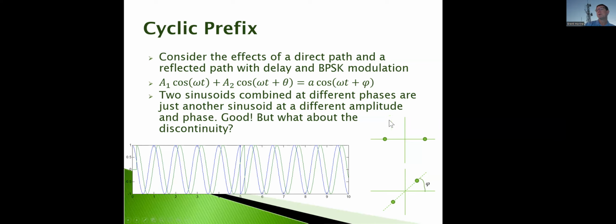So this is what we transmit, and this is what we're receiving, right? Because of this reflection. Well, we're already rotating as that wave propagates along, and we already have some attenuation. So our receiver already needs to compensate or equalize for phi and A.